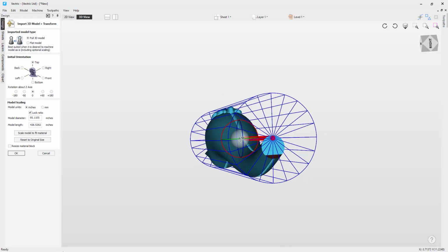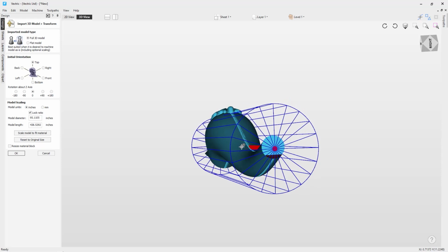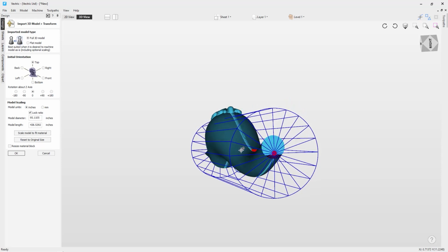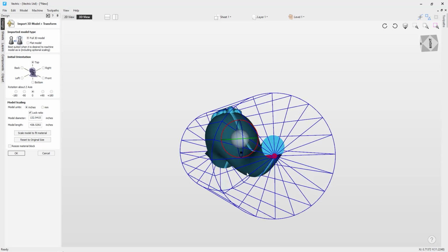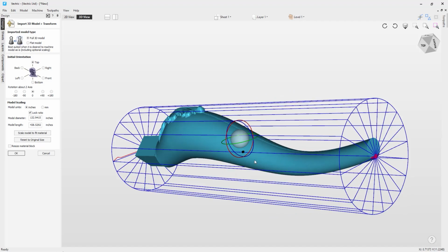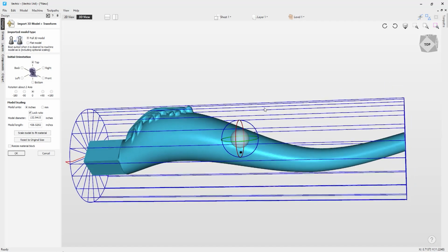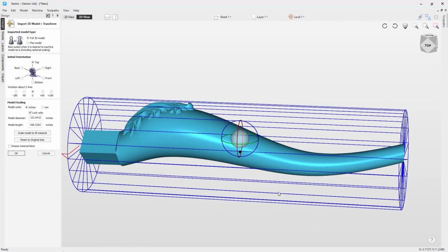So the aim here is, I want to drag this down so that the red is no longer showing. So I want to put this as central as I can into this table leg, but without any of that red axis showing, so we don't get any undercuts. Because what we're trying to avoid here is, with this dip section here in the table leg, if we left the axis where it was, you would get a lot of undercuts and a strange looking model in the end.